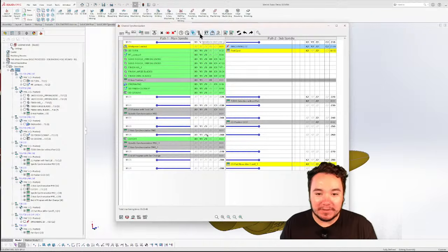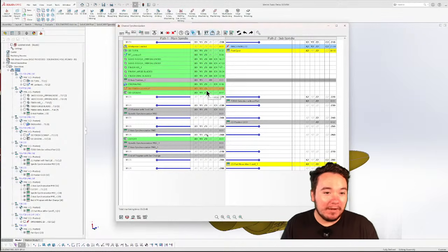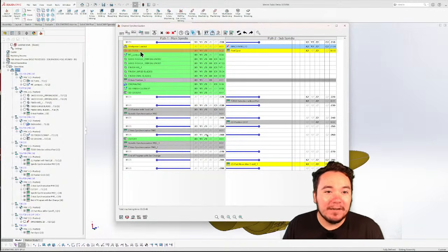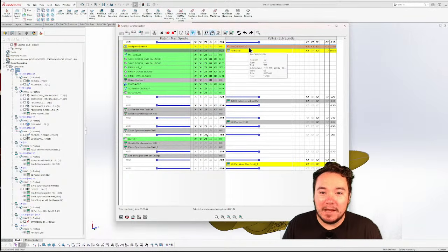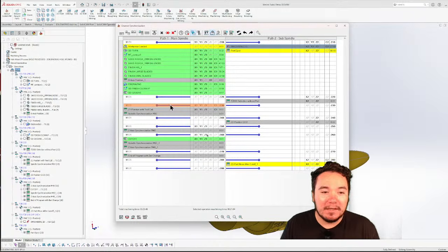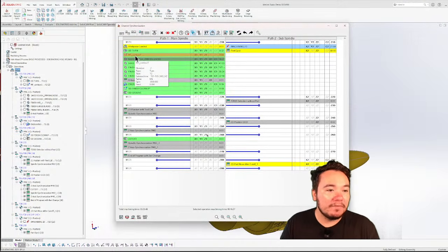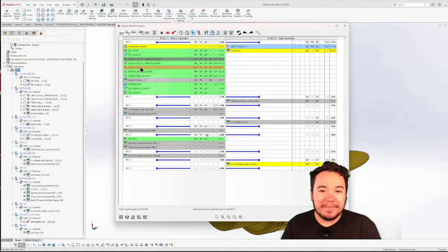We don't have any clashes. So right there we have synchronous cutting happening at the same time. The OD turn will happen at the same time as iMachining, and whenever the iMachining finishes, maybe in the middle of this 5-axis rough, which would probably happen because the OD turn and the manual turn, which is the finish, happen pretty quick.